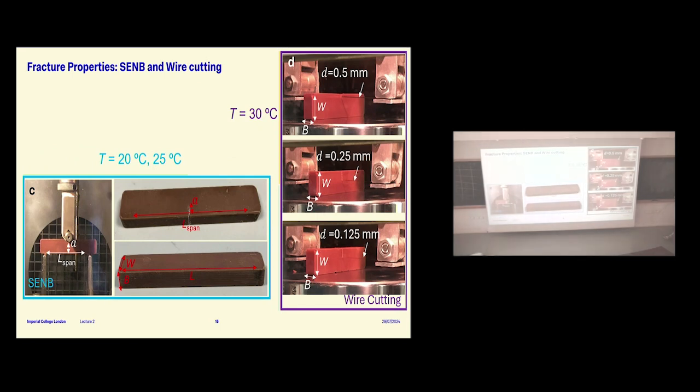Okay, the next thing I want to show you is that we did fracture tests. We talked about fracture mechanics again on Saturday. This is a common test here that we do for solids. So you have a beam where I'm not sure you can just about see it. You make a notch, a pre-notch here in the center of length A. And then you support this at the two ends, and you have a probe at the top, and you push it down. Okay? And then you measure the load and deflection. As that crack here, there's a crack here, it will start growing.